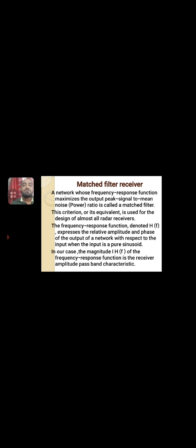Along with these three, it will have the Doppler frequency shift also, which will give the velocity of the target, and of course depending upon the amount of echo power that is received, we can estimate the size of the target. Above all, the limiting factor of all the radar systems is its noise. Now we have to study the performance of the system in presence of noise.